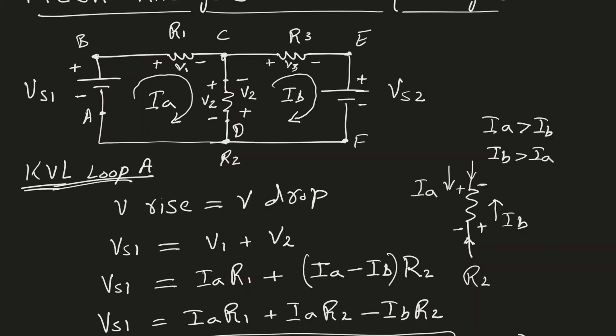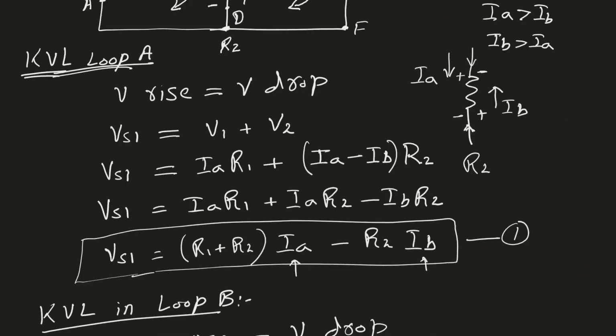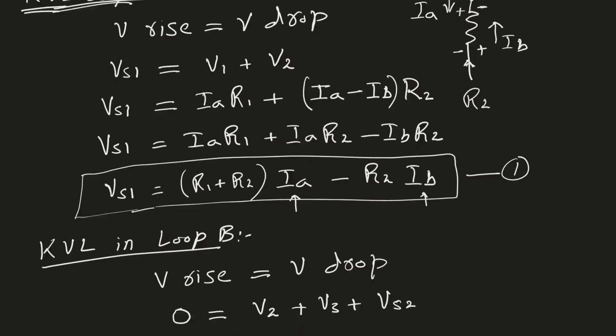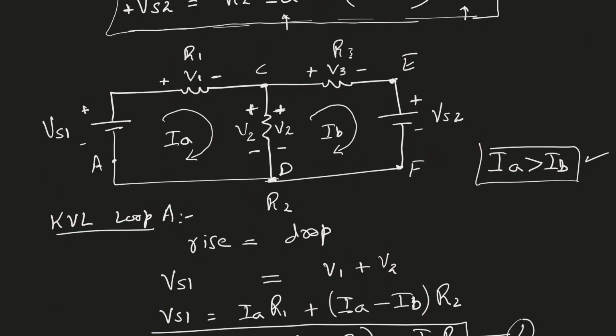All right, so that can work for you. Or if you don't like that method, because you see the problem with that method is that V2 gets opposite polarity in both the loops. So if you do not like this to happen, then you can choose this method: let's fix the direction of V2 and apply the two currents and then solve KVLs.